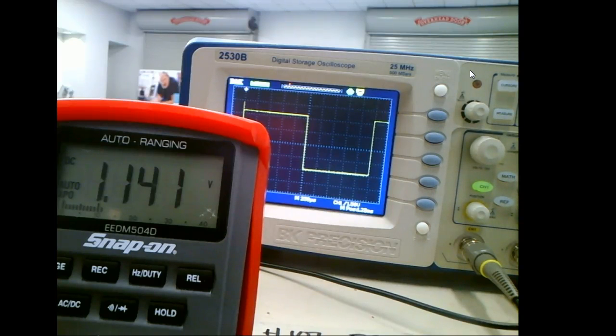So what I can do now is control the speed, and we can do this electronically. Because what I'm doing is turning on these solid state devices wide open, which means they don't produce a lot of power because they have very low resistance, or I turn them off. So now we can control a lot of power with devices that are not that big, right? You understand? Which is really, really cool. And this is the method I use.